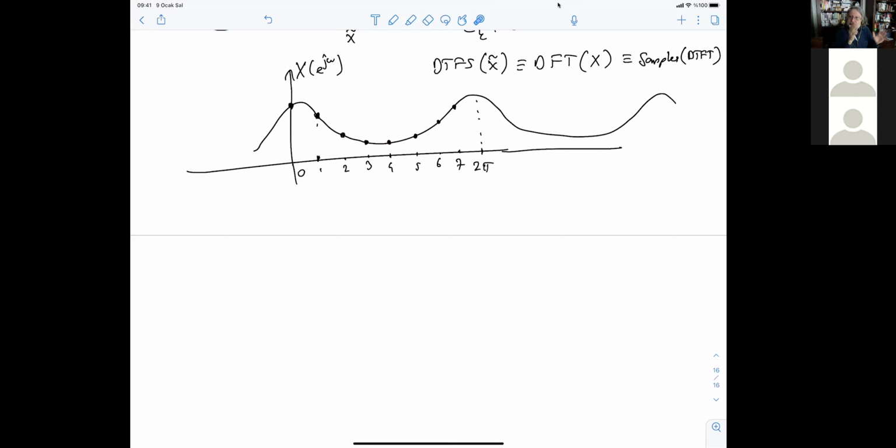And that half of it is still capable of further elimination of some of the samples. For low-pass signals like this, for example, if these values are large and the middle, central values around the high frequency, this is 2 pi, so the center is pi, those values around pi are irrelevant or there is no such content, you can get rid of them.